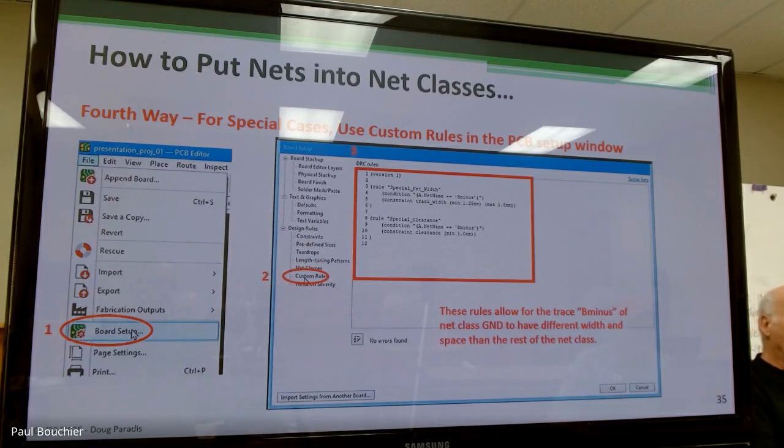They do make one nice thing down right here, a syntax checker. Whatever you write up here, you hit the syntax checker, and it reports. You see it's reporting no errors found. If you want to see an error, select the first line, version 1 with the brackets, and do a Control X or cut. Then hit the syntax checker, and you'll see it reports the required version is missing or something like that. You see that? Did it give that error? Then put it back with a Control V.